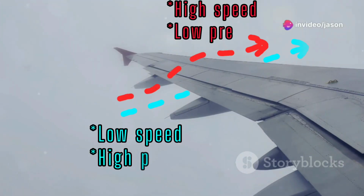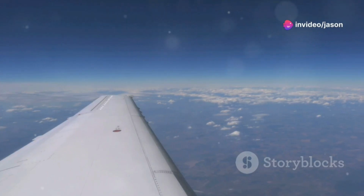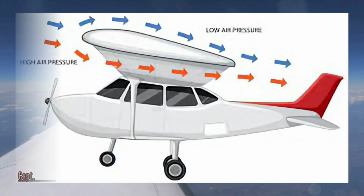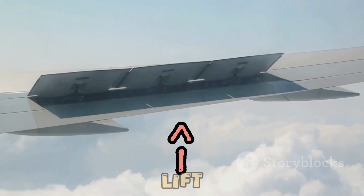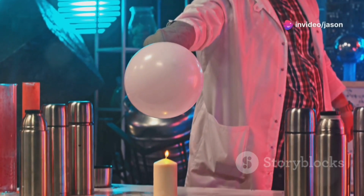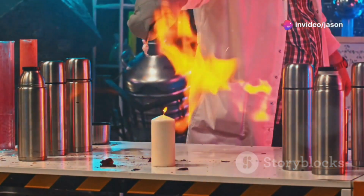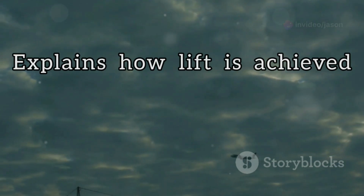And according to Bernoulli, faster moving air creates an area of low pressure. Meanwhile, the slower moving air underneath creates an area of high pressure. This pressure difference generates lift, pushing the wing upward towards the area of low pressure. Bernoulli's principle is like magic, but it's really just clever physics. It explains how aircraft defy gravity and soar through the sky.